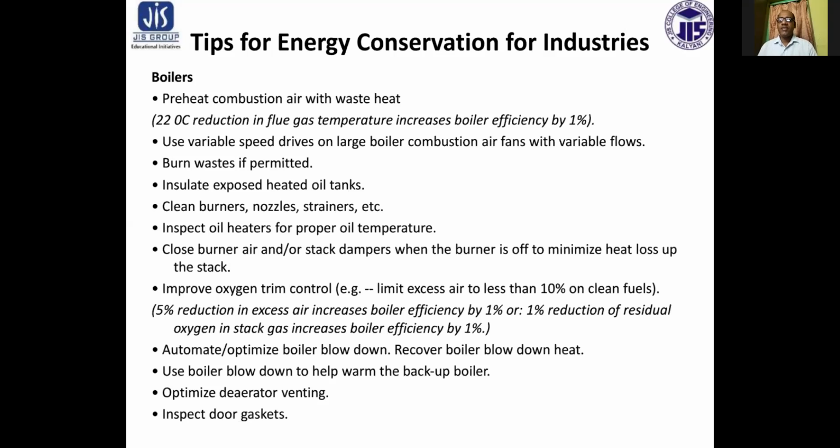Otherwise, if the temperature rises, it means there is wasting of heat. That means some malfunction is there. Close burner air and or stack dampers when the burner is off to minimize heat loss up the stack.